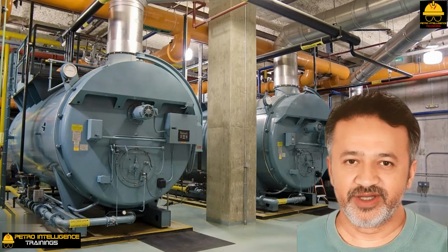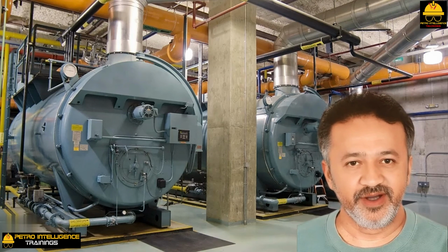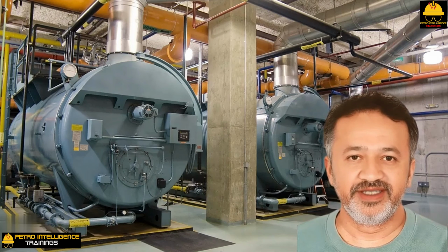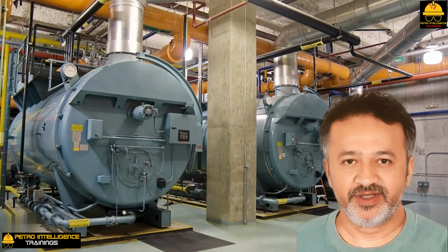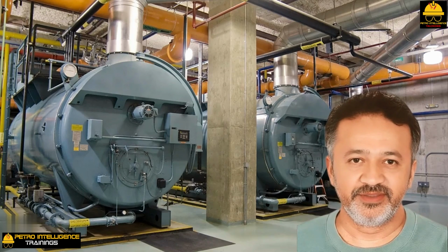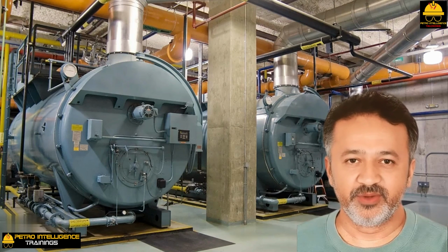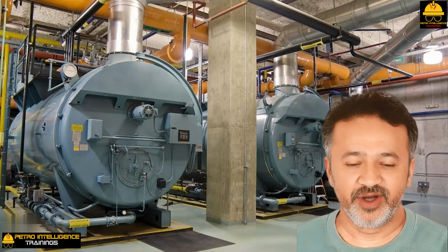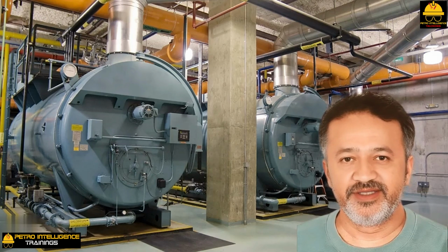As a young engineer, I had learned that cooling water should not be heated above 125 degrees Fahrenheit to 135 degrees Fahrenheit to avoid laydown of hardness deposits inside the tubes of water-cooled exchangers. What I had failed to grasp was that once water has been through a demin plant, there is no restriction on how high a temperature that water can be heated.